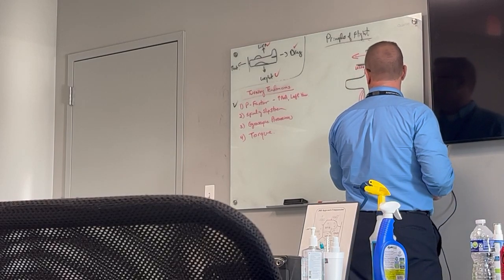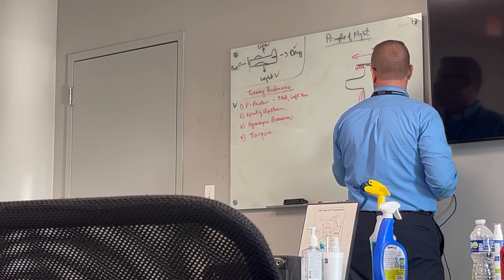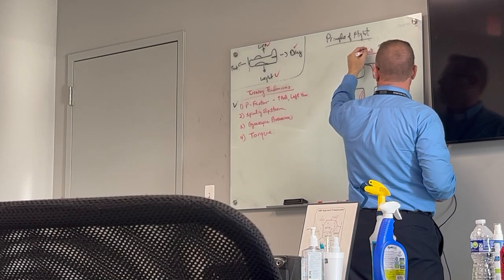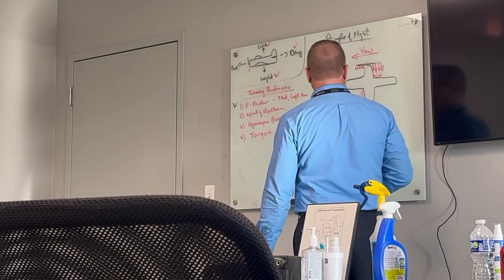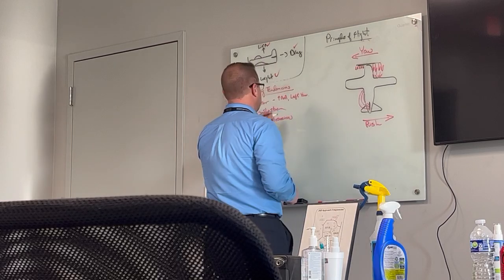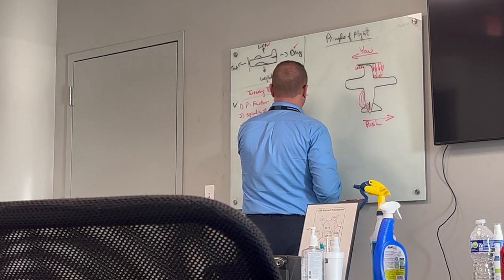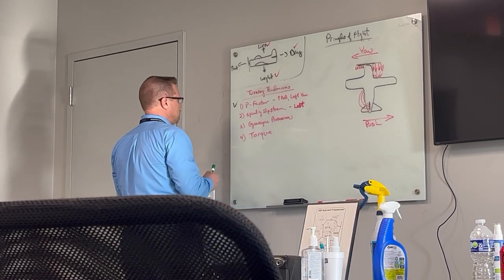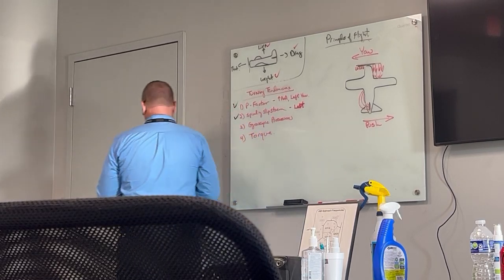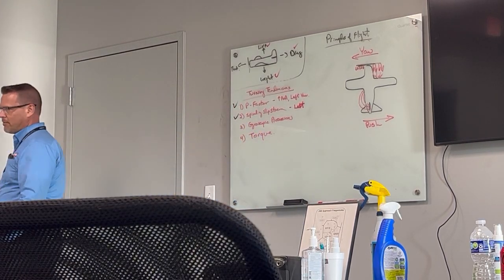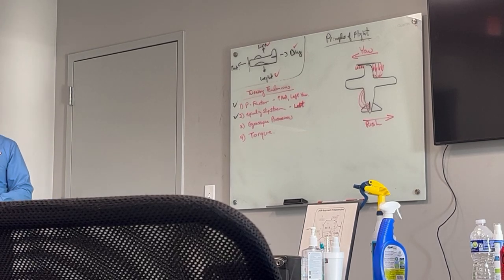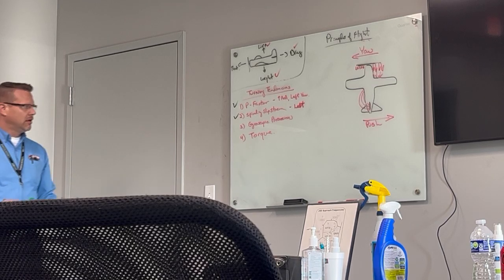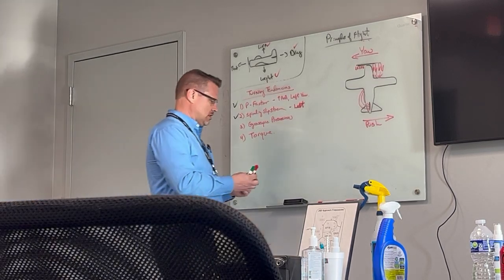So that causes a push in this direction and causes a yaw in that direction, right? So again, this would be a left turning tendency from the air hitting our vertical stabilizer on the left side, from the spiraling slipstream that's generated from our accelerated slipstream from the propeller itself. And again, it would be greatest at high angles of attack.